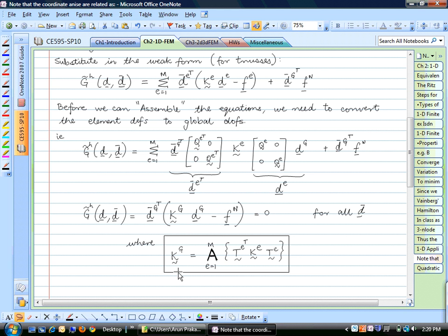Okay, and the only thing new about this truss problem is that you calculate your element stiffness matrix, append it with the appropriate amount of zeros, and then transform it to the global coordinates and assemble it. That's all the difference between a one-dimensional problem and three-dimensional structures which have individual elements that act in a 1D way.